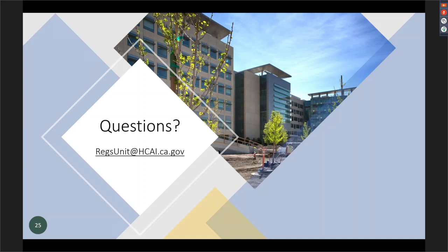It's right in the code. Any change to the approved construction drawings must be stamped and signed. Even if an RFI changes the drawings, in theory and by code, it should be stamped and signed by the design professional noting a change. That in itself would be converted to an NMA and given to us for concurrence. That is something that has been in the code for several years.